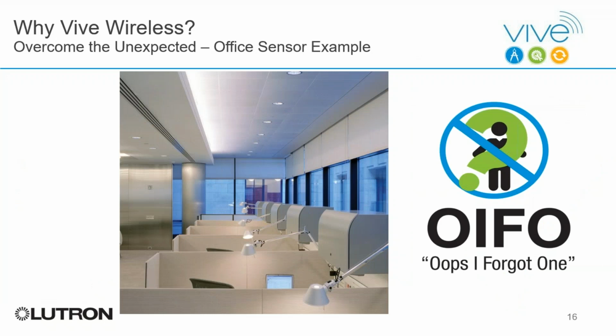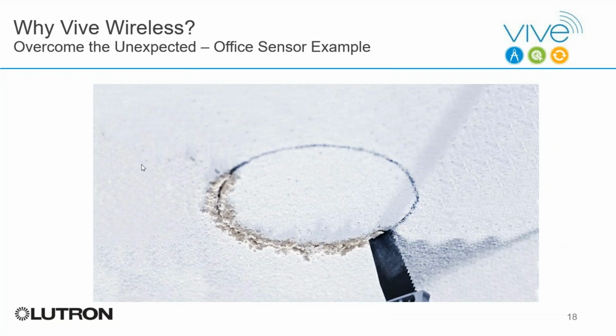Another example, and we've seen this a lot, there might be some confusion in terms of the specification. So let's say, for instance, in an office, you thought that it was going to be a time clock control, but instead the owner says, no, our corporate standard happens to have been aux sensors, and that was missed. Well, that would be a problem, right? Oops, I forgot one, or several in some of the cases I've been involved in. Now, if you were doing a wired sensor, you'd have to go cut a hole in the ceiling, you'd have to mount the power pack, you'd have to mount the low voltage wire between the two, connect it to the high voltage, and you have to do that over and over and over again.